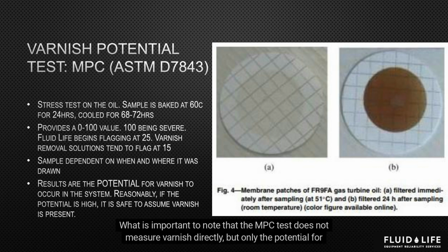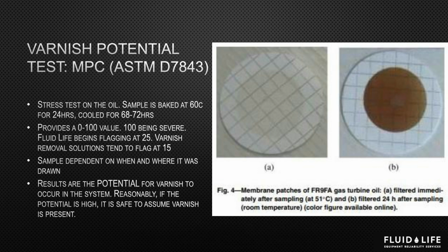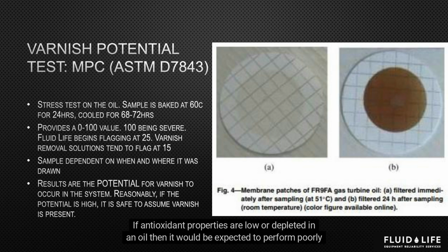What is important to note is that the MPC test does not measure varnish directly, but only the potential for varnish to occur. If antioxidant properties are low or depleted in an oil, then it would be expected to perform poorly in this test.